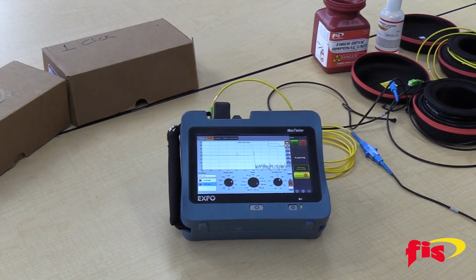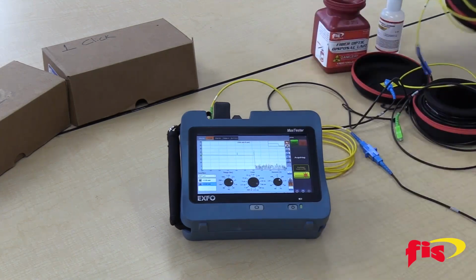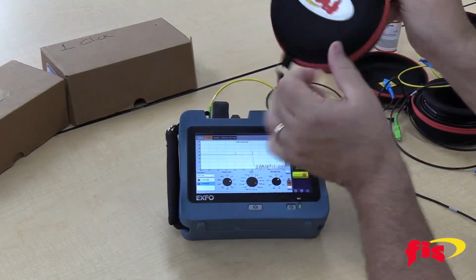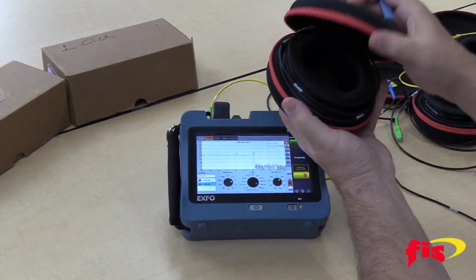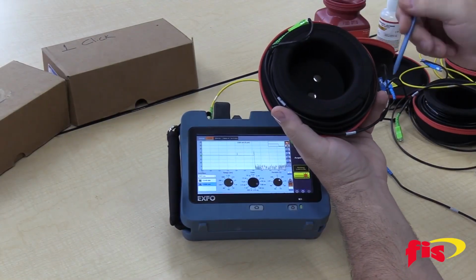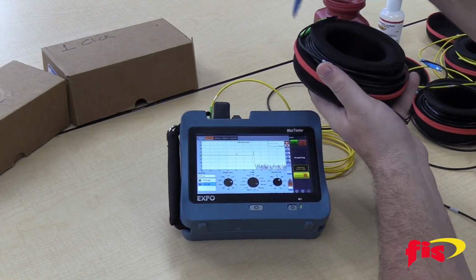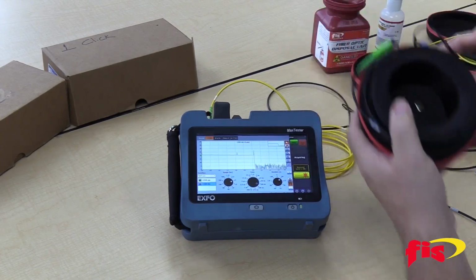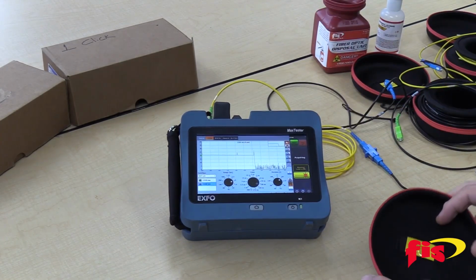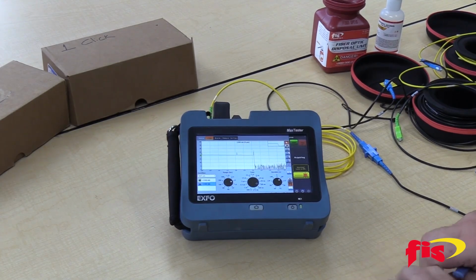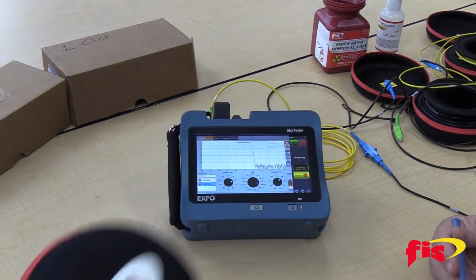Now, the launch cables that we use, this is a nice short one, and I think we can get like 150 meters or so. Again, this is a little hockey puck style. You can have either connector style you'd like, and the fiber's underneath here, and we just have the leads that we can access. For single mode, could you use a 100-meter launch cable? Sure. I always err on the side of longer is better. So for single mode, I usually recommend 500. So it might be in a larger case than this.